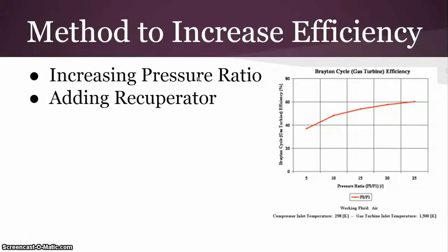First of all, increasing the pressure ratio increases the compressor discharge temperature. This can cause the temperature of the gases leaving the combustor to exceed the metallurgical limits of the turbine. Also, the diameter of the compressor blade becomes progressively smaller in higher pressure stages of the compressor. Because the gap between the blades and the engine casing increases in size as a percentage of the compressor blade's height, as the blade gets smaller in diameter, a greater percentage of the compressed air can leak back past the blades in higher pressure stages. This causes a drop in compressor efficiency and is most likely to occur in smaller turbines.